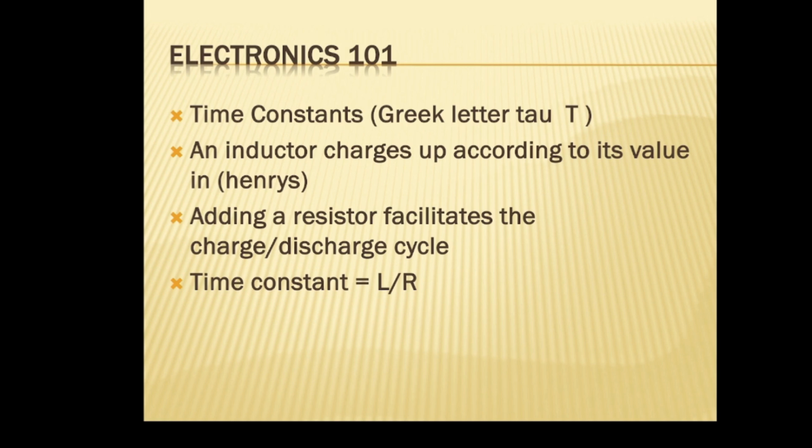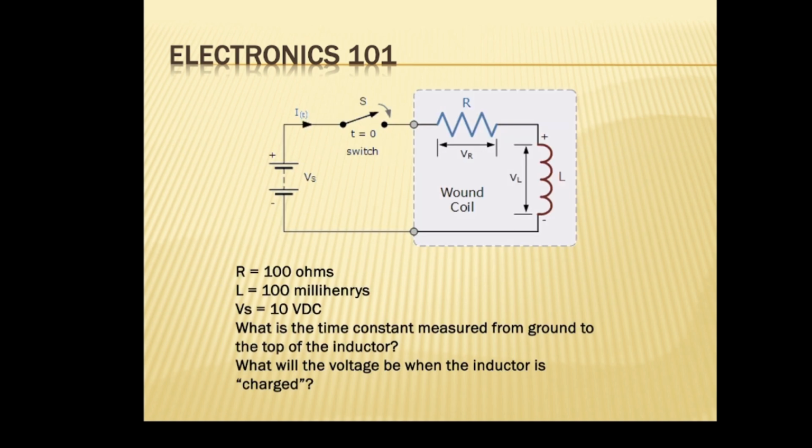Now, we really get sophisticated. We put an inductor, a capacitor, and a resistor in there. Then we can really start fine-tuning the thing and make it do some real work. This is the same circuit, but we're not going to build this one up because our time is just getting away from us, but you get the idea here. The same thing we did before. Now, generally speaking, these time constants are going to be much shorter than with the capacitor, so we wouldn't be able to see that much of a change in the inductor, but the idea is the same. And we can calculate the time constant with division. We're not going to talk about that a lot.